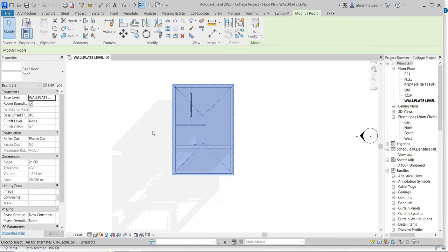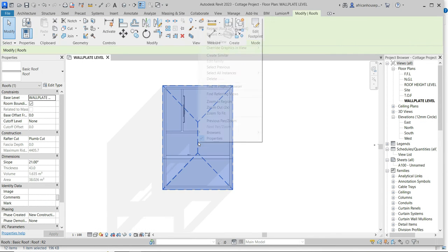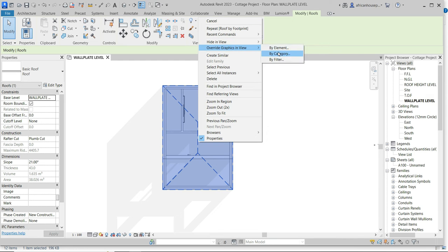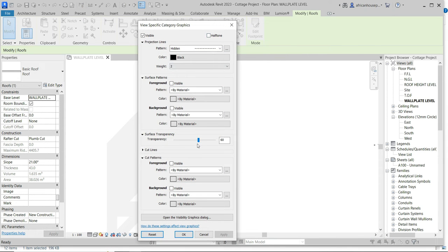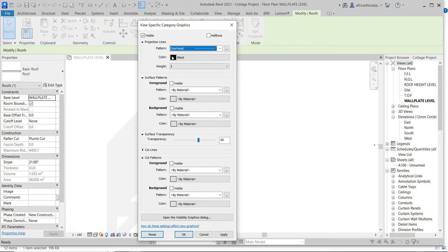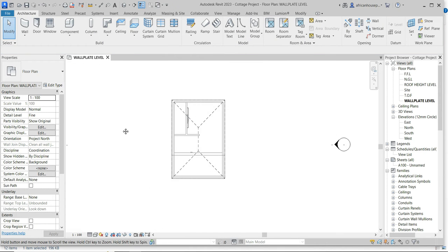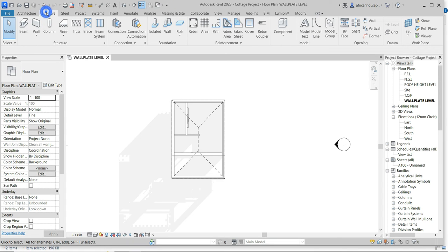Okay, perfect. The reason why I saw the roof is transparent like this is that I came here and made it transparent. Let me change it to any type of overhang. Let's make it 1. And then I made it transparent, I adjusted this transparency so I can see what's going on underneath. Then the next thing is to add roof trusses.